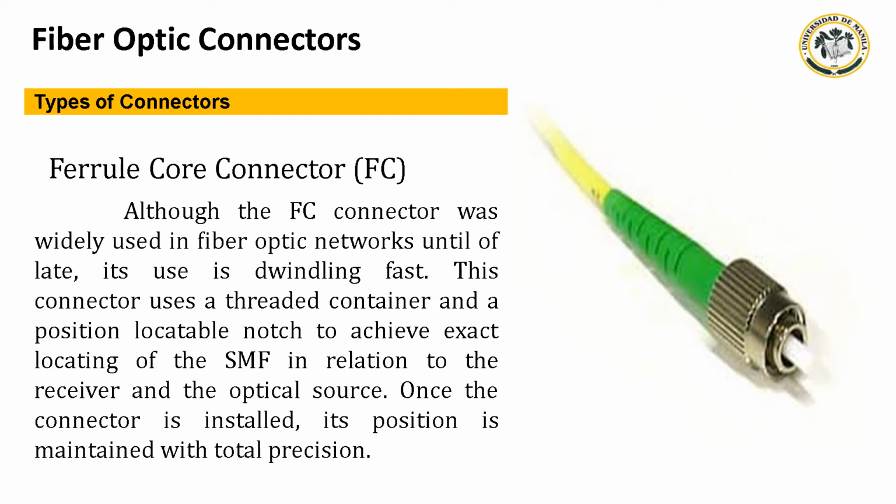These deliver similar performance to the FC, but both have less expensive components and are quicker to connect. However, the screw-on collet of the FC does make it particularly effective in high vibration environments, ensuring that the spring-loaded ferrule is firmly mated.